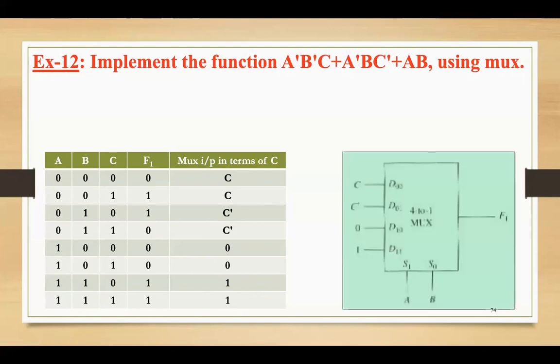So we are going to have this D flip-flop, right? MUX with combination, and whatever is here, the C, C bar, 0 1. So accordingly we are going to take based on the AB combination. So AB is going to be our select line, 0 0, 0 1, 1 0, 1 1, right? So based on that we are going to get the outputs.